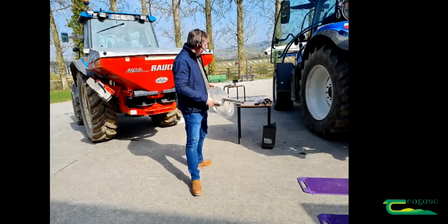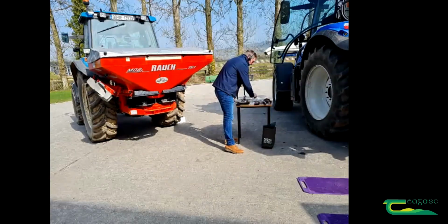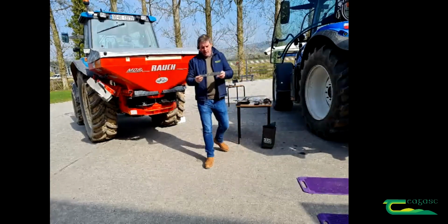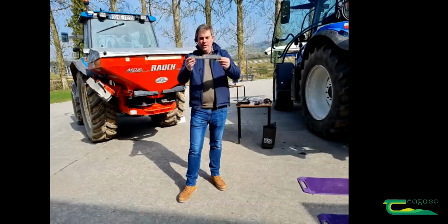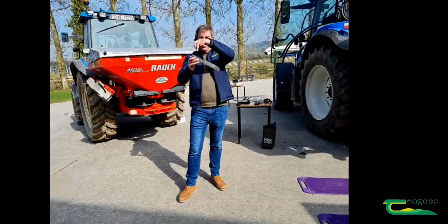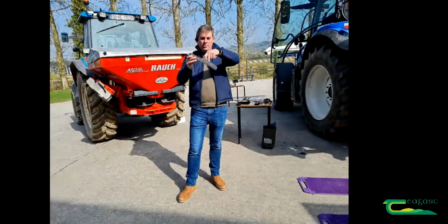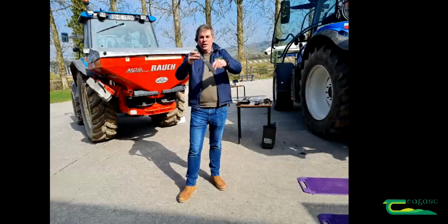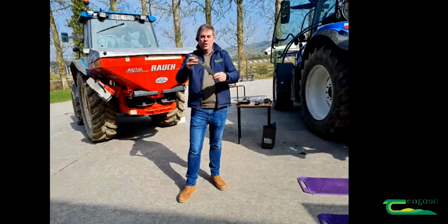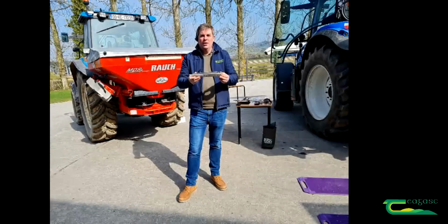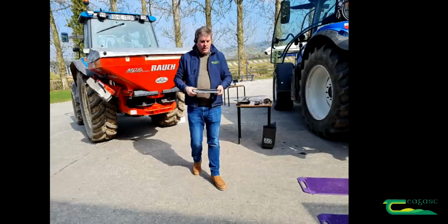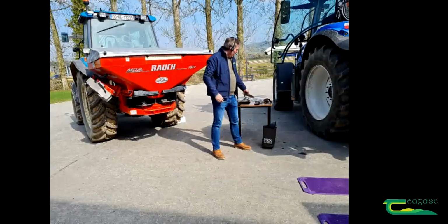And I suppose if you can imagine, if we just take the vane here, essentially what you're doing is changing that angle. If we're looking at that horizontally, if the fertilizer lands on this, it's going to move off it reasonably quickly. If I change that even further, it's going to move off much quicker. The steeper I come up, the longer that fertilizer is going to spend on the vane. The longer it spends on the vane, the more energy it's going to get, and the greater distance it's going to travel. So getting that angle right is important.